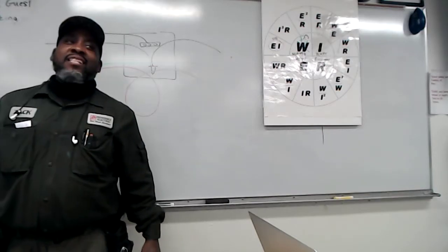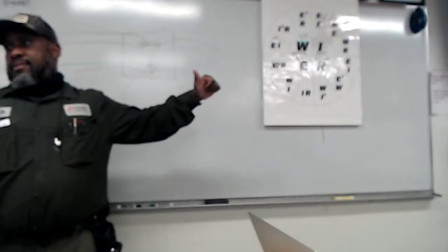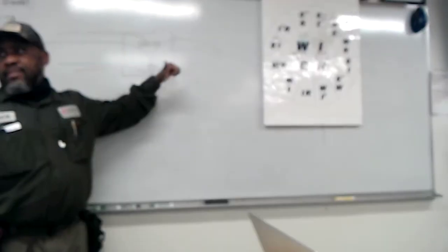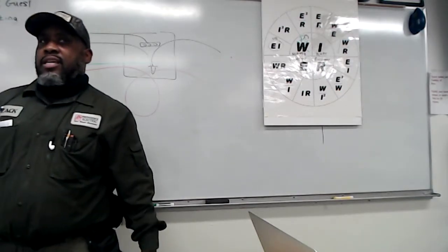300.14 says conductors need to be 6 inches outside the box. So if you grab that loop and it's 6 inches, one side is 6, the other side is 6. Then that's 12 inches of loop in that box. It gets counted how many times?